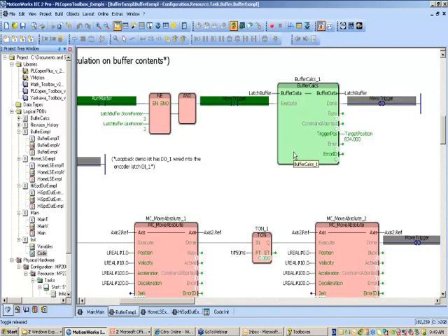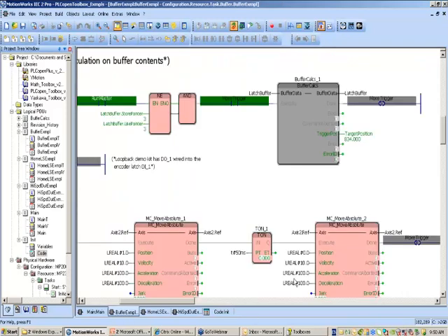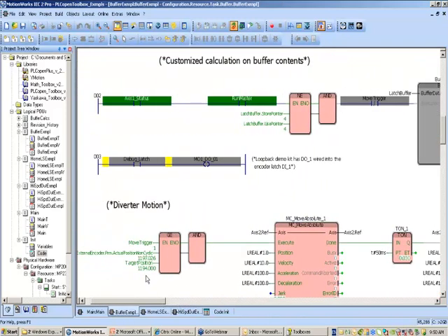And inside here, we take in the buffer data at my use pointer location, the non-cyclical value, use things like the sensor distance and the manual offset to create a new target position, and then I update the pointers, just like this. So here's my customized calculation, setting a new target position, and then making moves.